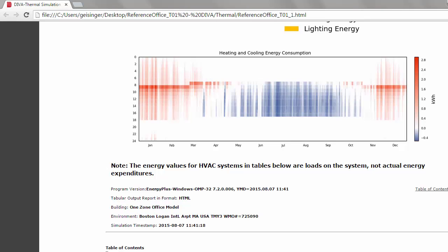And so you'll see that in the winter, we typically have an increase in heating energy consumption at the start of the day because this is when our setback turns off and then our set point turns on. And so the temperature for our energy balance increases, and the energy needed to heat that space has to jump and exert itself even more in order to maintain comfort levels inside the space.